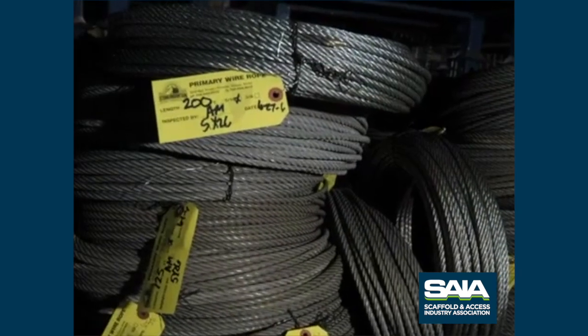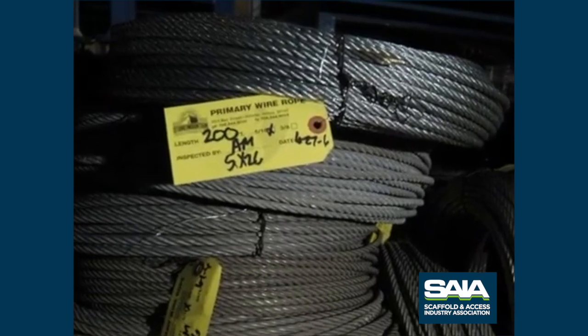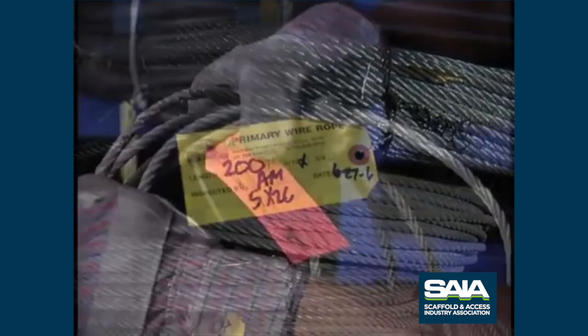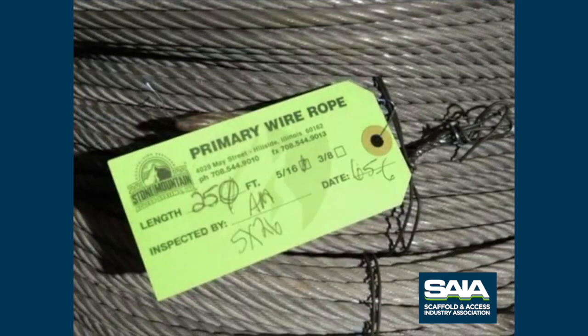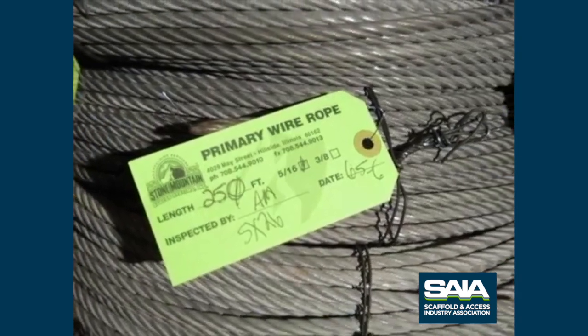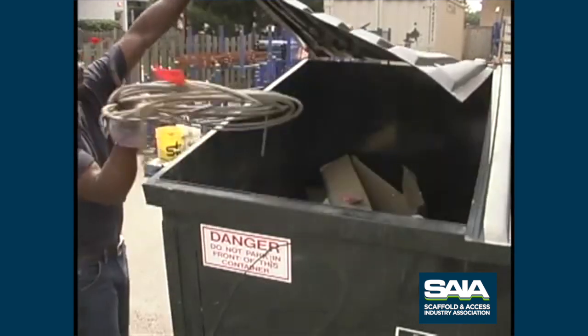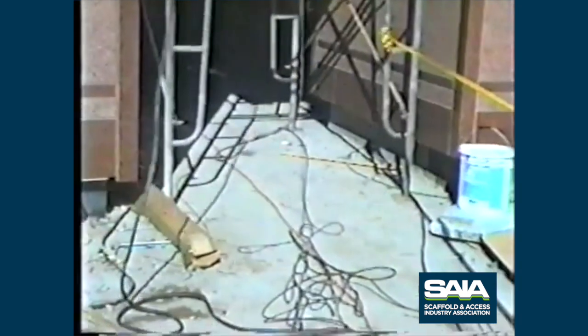All rope should be tagged with condition, length, and construction marked for easy identification. This will help match the rope for the equipment and the job. For example, red equals needs inspection. Green equals ready to be used. Make sure to red tag, destroy, and discard bad rope to prevent it ever being used.